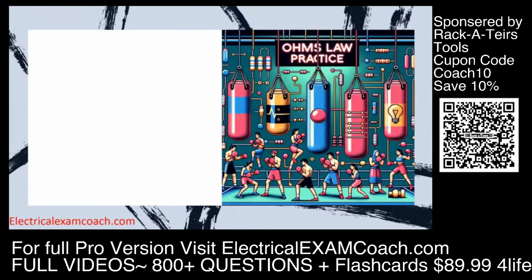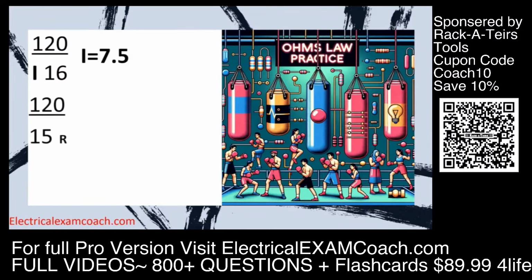All right, let's do some Ohm's law practice. You can do it. I'm going to go a little bit slow here, so if you want to pause the video and try it on your own, you can. We have 120 volts. We have 16 ohms of resistance. What is the current? That's right, it's 7.5 amps. All we had to do was take 120 divided by 16, and that lets us know that we have 7.5 amps on this circuit.